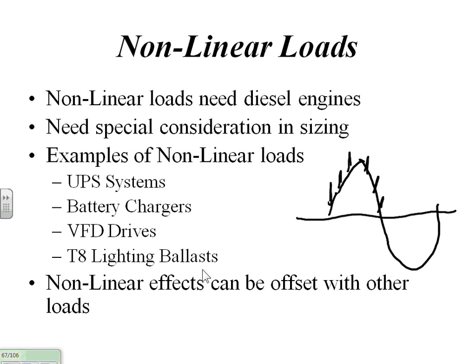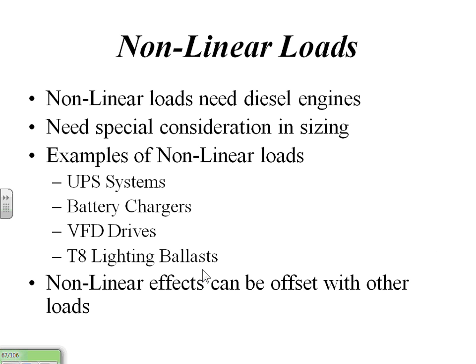Uninterruptible power, because we're doing exactly that, and it notches the heck out of the waveform. So that's an old thing, but that's the nonlinear load issue, and you see it in VFD drives and that kind of thing too. They do run better on diesels, but a lot of natural gas sets, there have been other things to come along to help fix that issue.